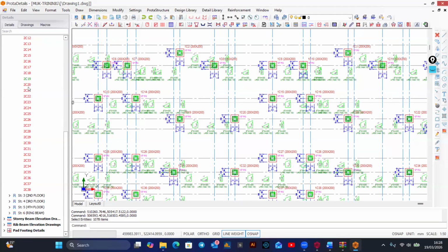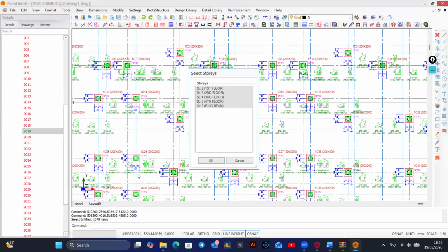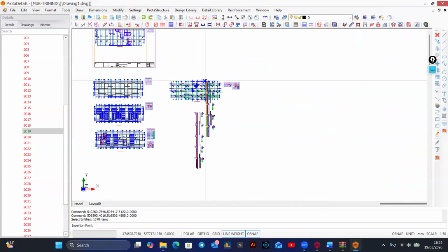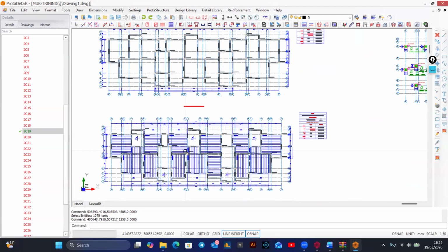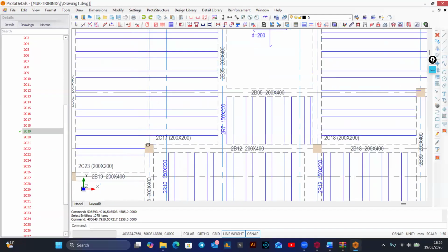Also, those columns that have a change in level, those that are terminated at terrace level, those that are continuing, all have different column IDs. You choose one among them and export it through stories. I'll right click on one column elevation, export through stories, and then add it here. I'll identify one column which ended at the terrace level, for example, this C17.